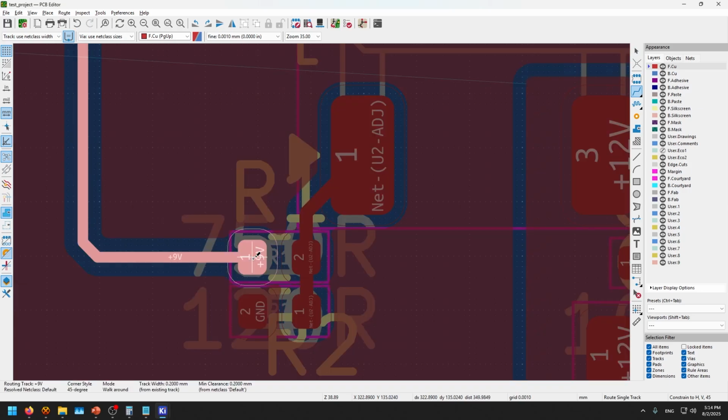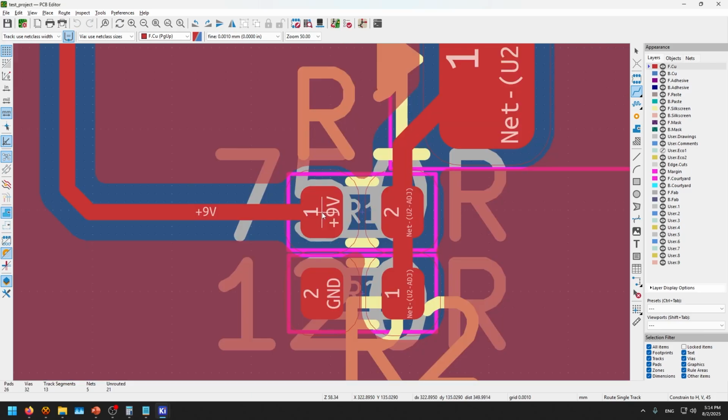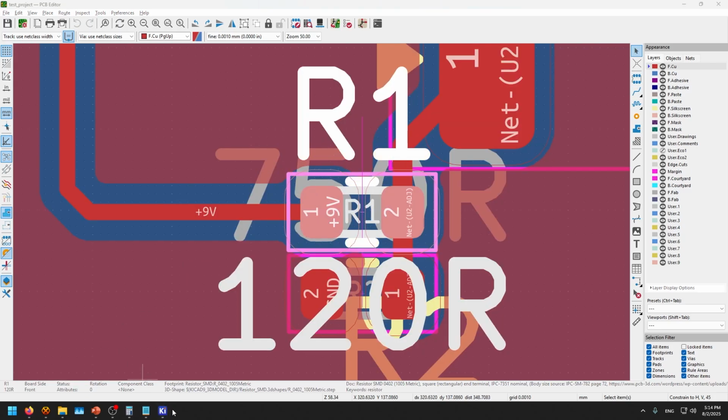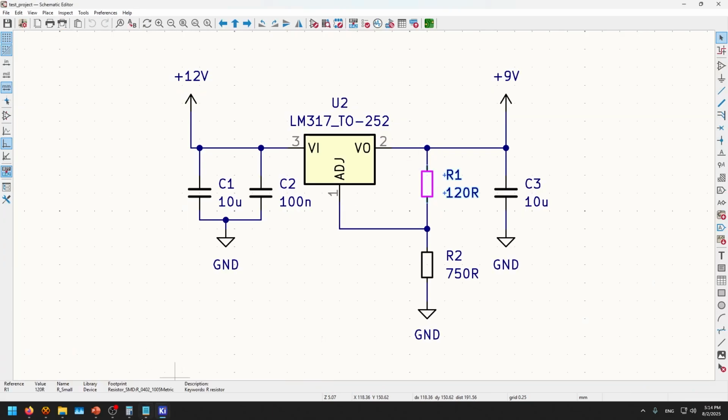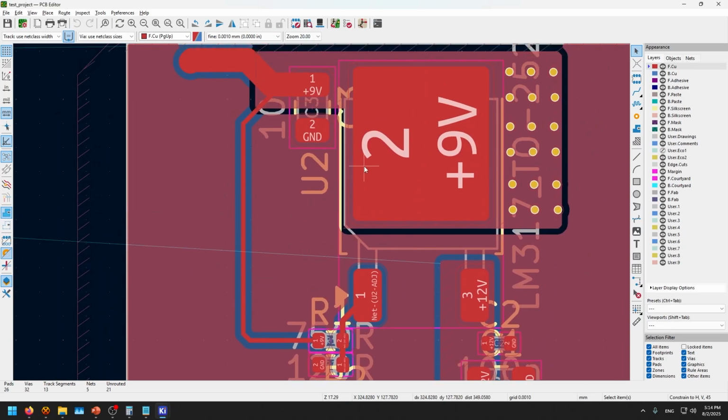But when you take the output from the output side and deliver it to the feedback resistor, which is this node right here, you need to take it basically not from the output pin itself, but from the point of load. Let's call it that: the point of load after all the capacitors and just before it gets out to your circuit, because you don't want to take it from here and have some voltage drop happen right here and ruin your value.